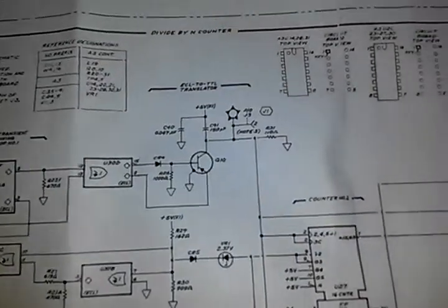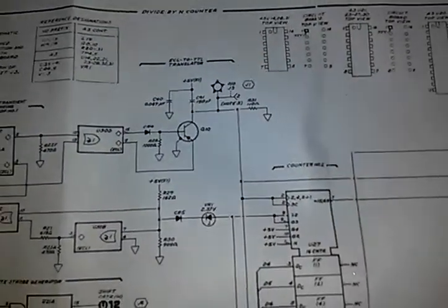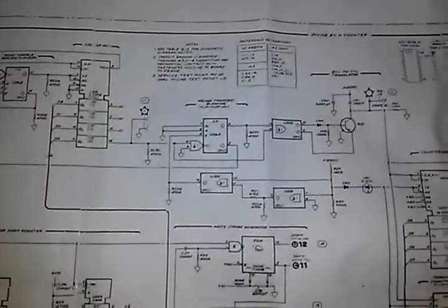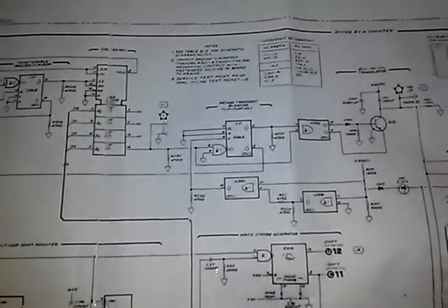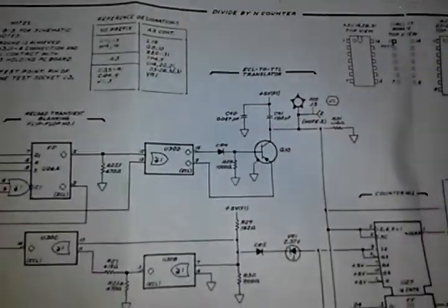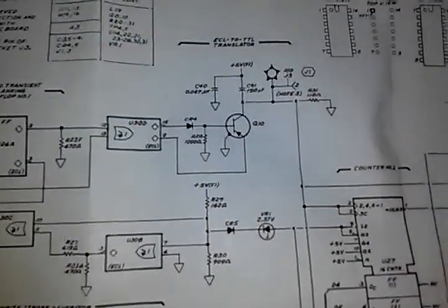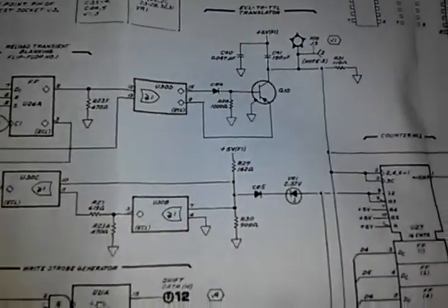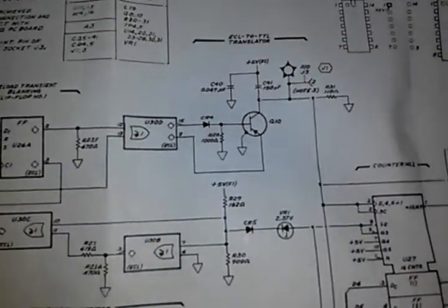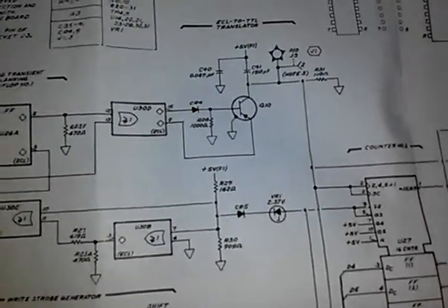The point is that did not fix the problem, and in a way, Alberto, and if you're watching, Alberto, who is one of my viewers, me and Alberto go way back to when I started doing repair videos on the TDS 540 oscilloscope. And he made a suggestion which turned out to be somewhat correct. His point is maybe it's out of frequency range. Maybe this thing is being clocked at a level that is too fast, and that's the reason why it's clipping the proper TTL level.